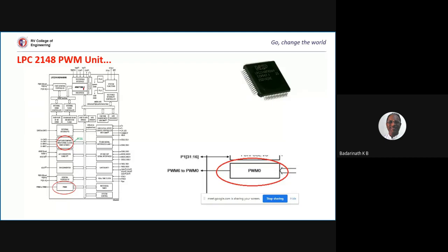You just instruct the PWM hardware what is required, how many DC or servo motors you want to control, and the speed of running. That's all. You just identify your requirement, inform that hardware, and focus on other work. These hardware blocks will work independently as per the instructions given by the controller. This is an advantage of having PWM hardware built into the microcontrollers.